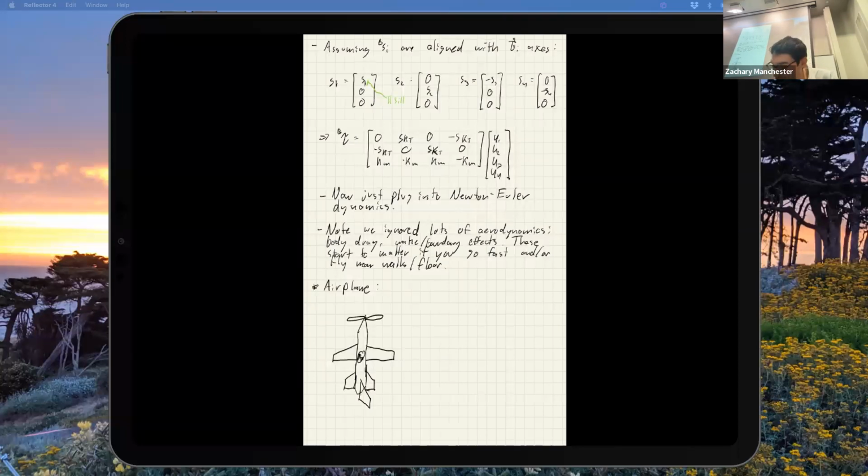Okay, so control surfaces. We got ones on the wing here. These are little flaps that I can actuate, right? What are those ones called? Ailerons, right? Those are for controlling roll. You actuate them together, where one goes up and the opposite one goes down, to get a torque. And then I got ones on the horizontal stabilizer back here that work together. These move up and down together to actuate pitch, right? What are those ones called? Elevators.